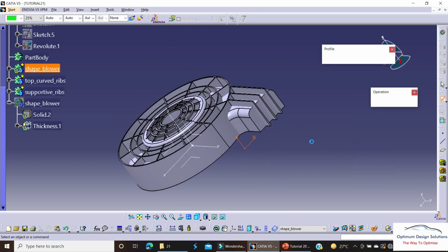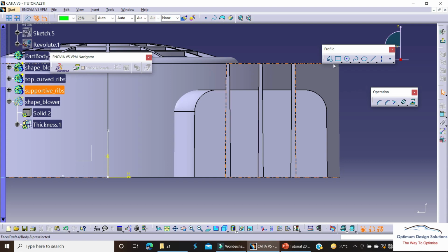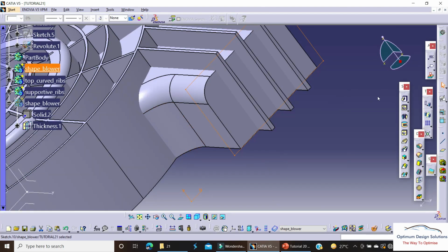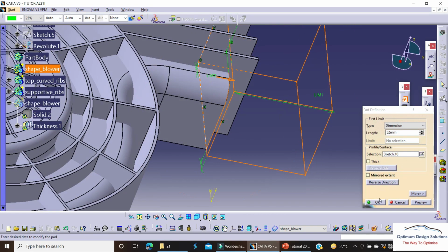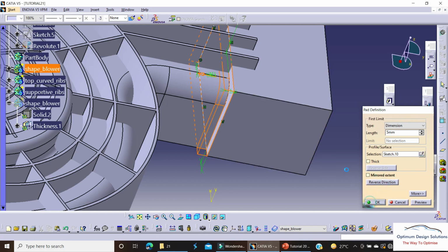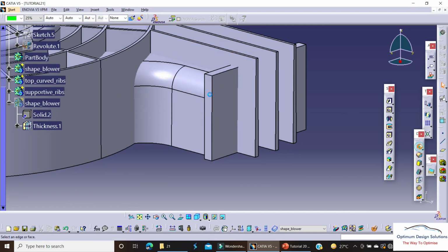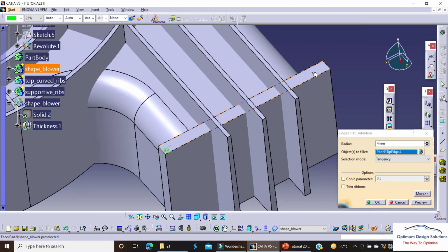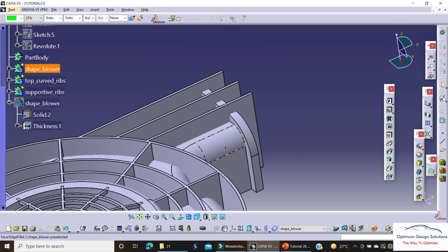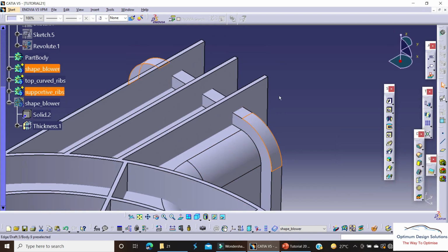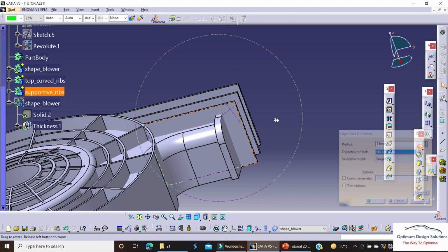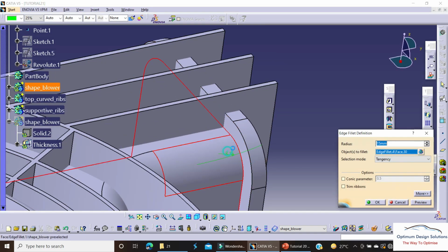So we'll increase the duct area, and for that we'll add one sketch here. Here we added 5 mm of extra thickness, so we'll use the pad command, 5 mm. We'll give the radius; 5 mm is not looking enough, so we'll convert it to 10 also, but before that we'll add the proper radius of 15 mm. So here you can see the duct area has increased.